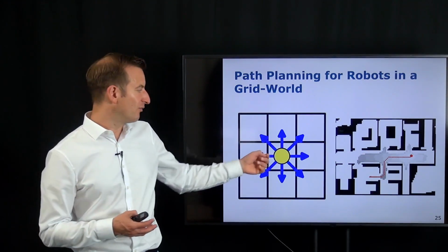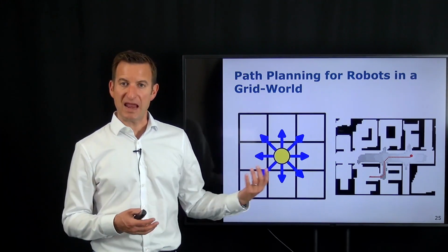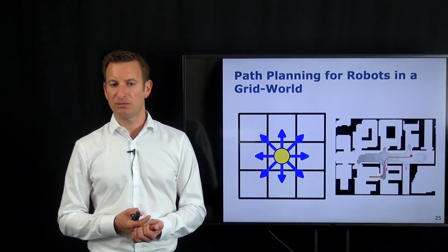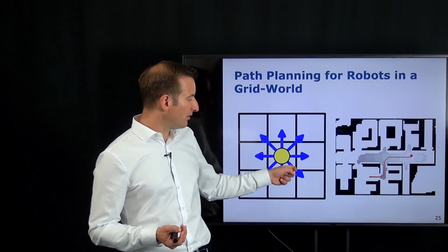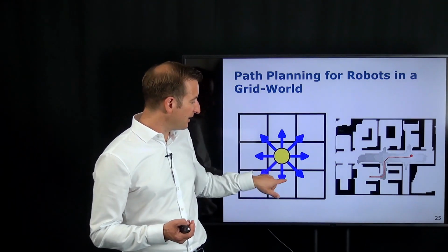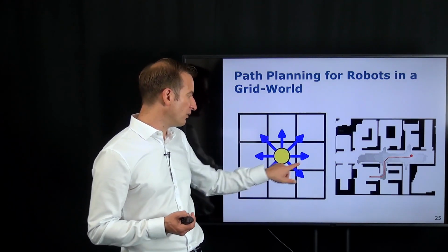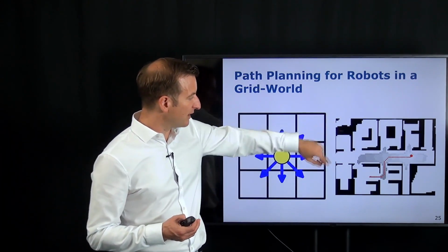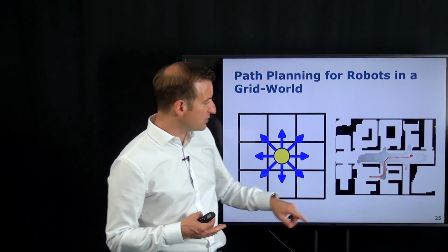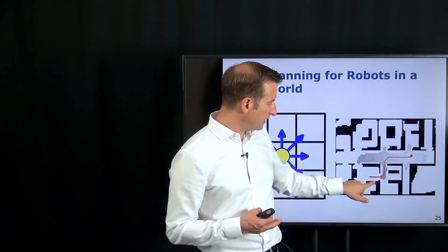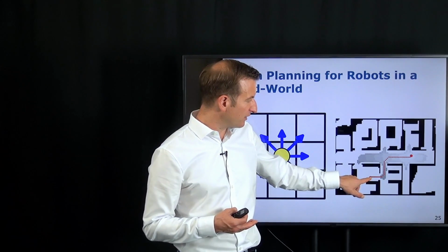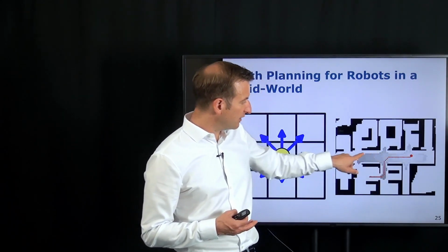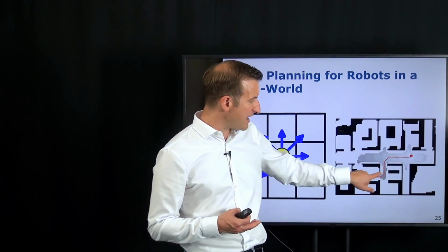This is, for example, the 8 neighborhood that we can take into account for planning. If I don't allow the system to walk diagonally, then I could use the 4 neighborhood where only those 4 neighboring locations are possible. And then if we have a grid map, where dark is an obstacle region, the system is right now over here and we want to reach this state over here, then I can expand the nodes and you can see it here, this grayish area.